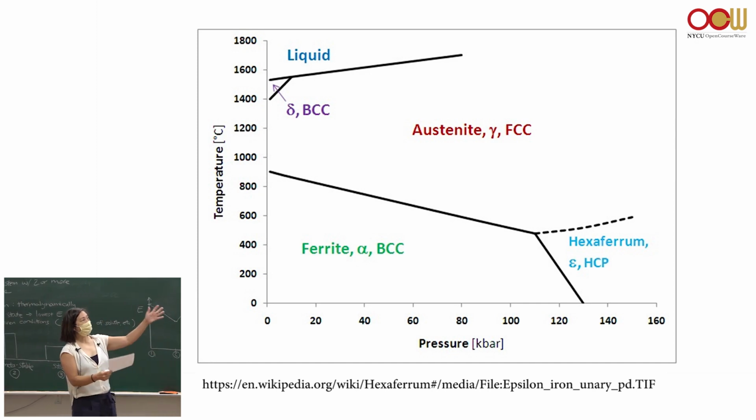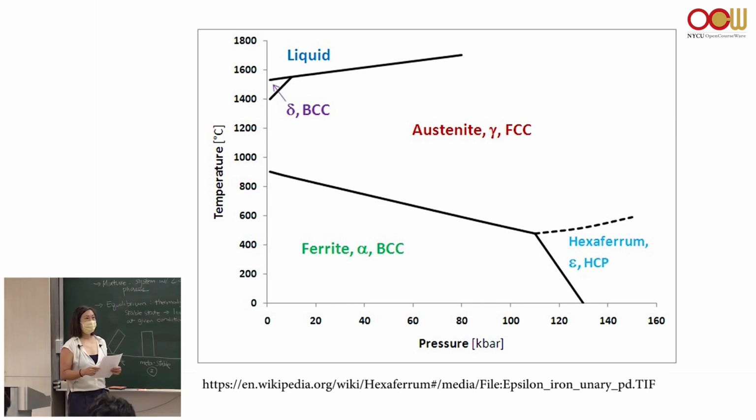So by looking at these diagrams, it tells us what to expect when we heat treat iron, right? If we heat iron and we want carbon to go in, we know, well, in BCC, carbon usually would go into the substitutional phase, but in FCC, carbon will go into the interstitial phase. So probably it's easier to put carbon into the interstitial phase because there are more interstitial sites. So we want to heat iron up to 1,000 or more degrees Celsius because then carbon goes in more easily. So that's very, very useful for us to have that information.